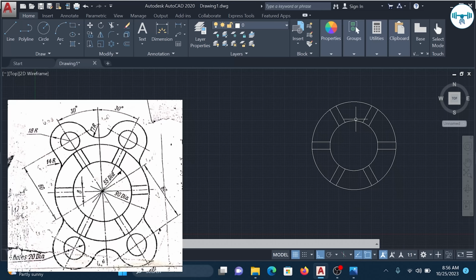Can you see them? These 4 circles, their centers are on this line that makes 30 mm with the vertical. So first of all, I'm going to draw that line, because when I draw the line I would have gotten the center of the circle. So the first step is to draw these inclined lines 30 mm with the vertical.